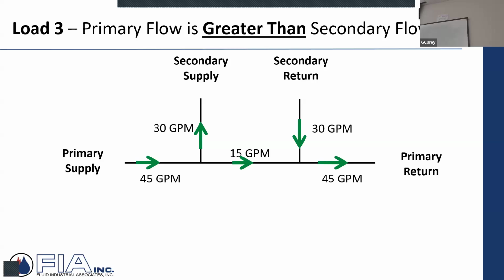So I haven't done any mixing. What have I done with it? Where's the mixing now? Then that becomes my diverting T, and this becomes my mixing T. So now I'm taking some hot boiler water. Some of it goes up through the load. Some of it stays across the common. Now I take this return cooler water and I mix.